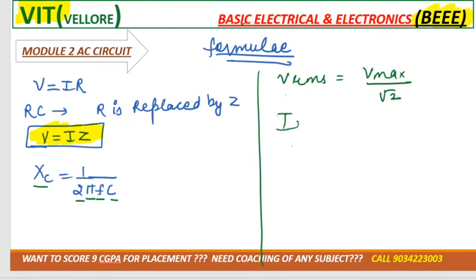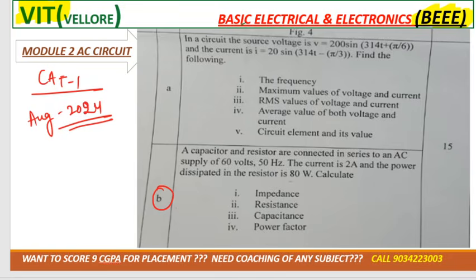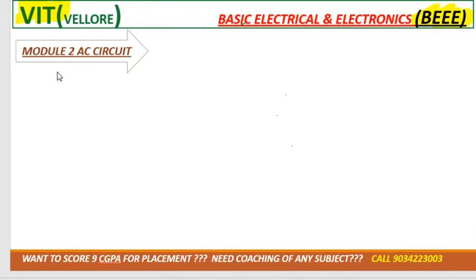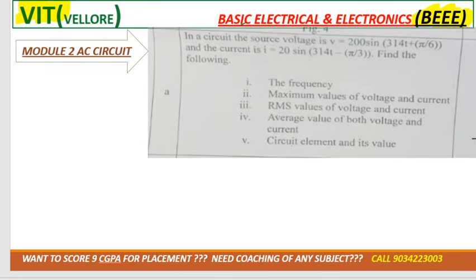Similarly, IRMS is always equal to Imax divided by root 2. Whenever they give you the equation, they'll give you Vmax, and we want to convert it into RMS. Clear? From this you can get it. If they give you in the form of an equation like this, where in this one they give 60 volt, that is the RMS, but whenever in a numerical they give you the equation, they'll 100% give you the maximum. Clear?